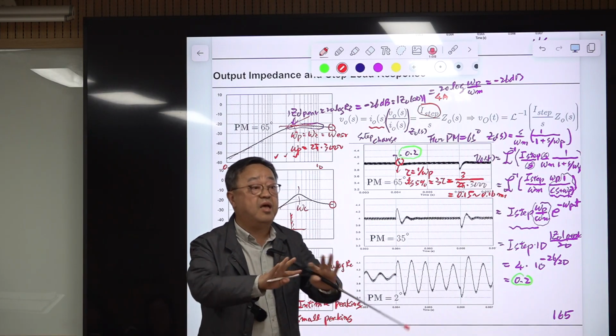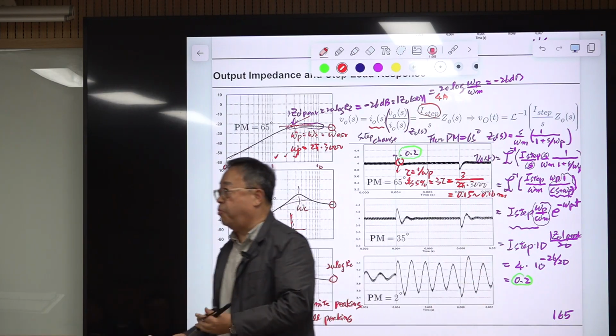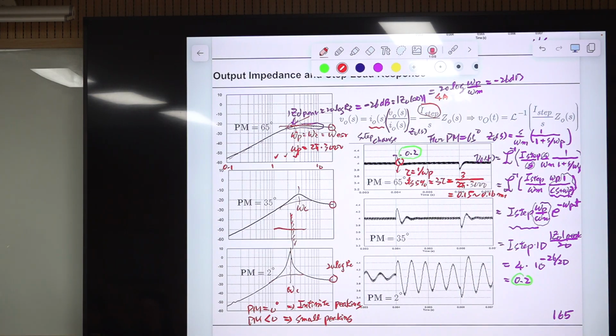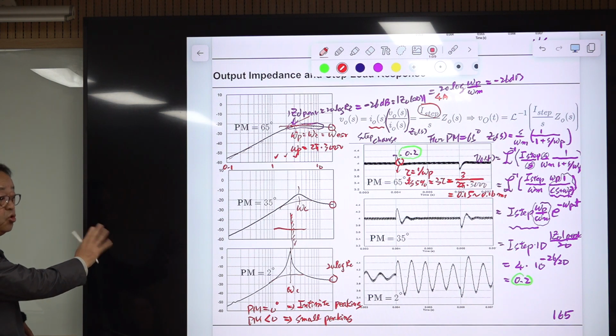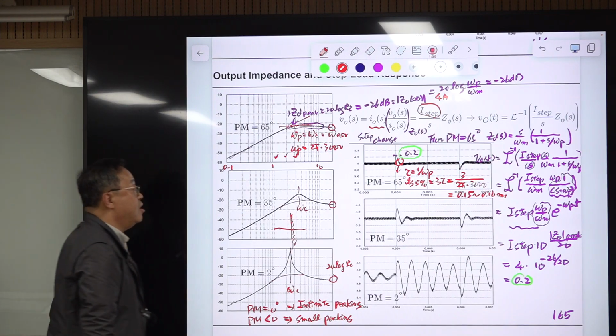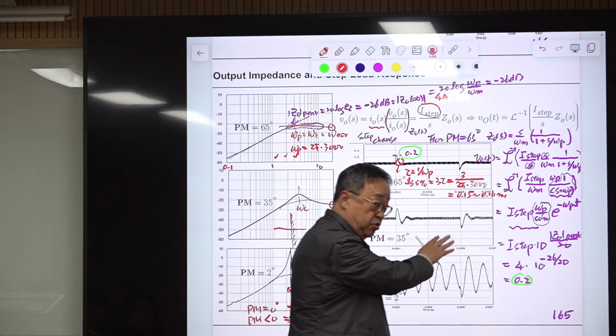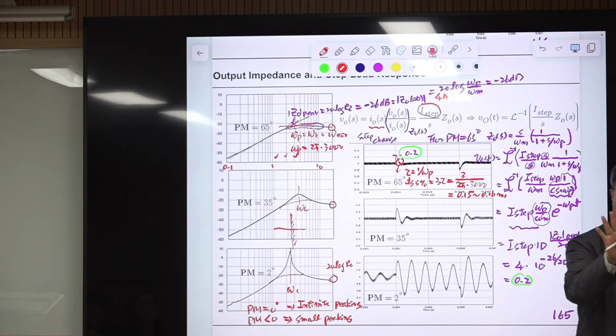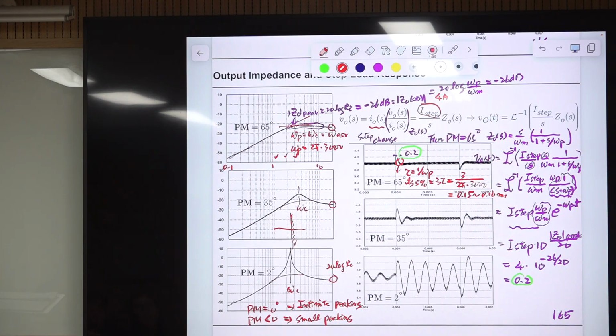Okay? This can be extended to other converters, buck boost converters, and also to other power converters, resonant power converters, or any type of power converters, isolated, non-isolated, like that. So this is the huge benefit of obtaining the small signal model of a converter. With the small signal model, you can freely use our knowledge of the linear time invariant system, just with care. We assume the disturbance is sufficiently small, okay? Then everything will be okay.